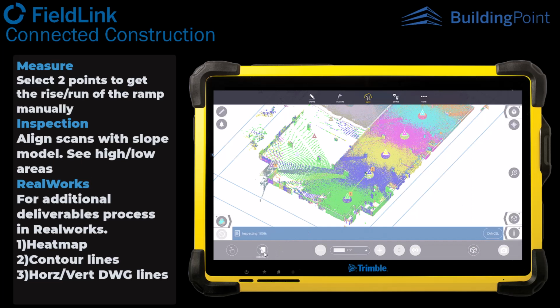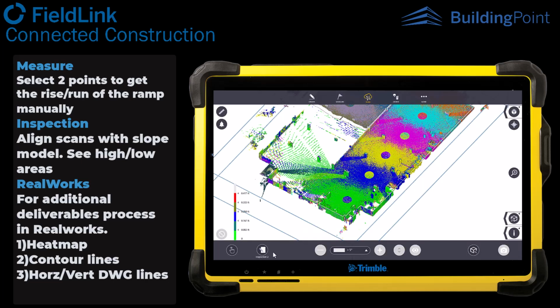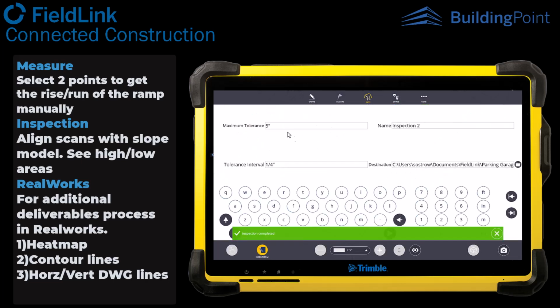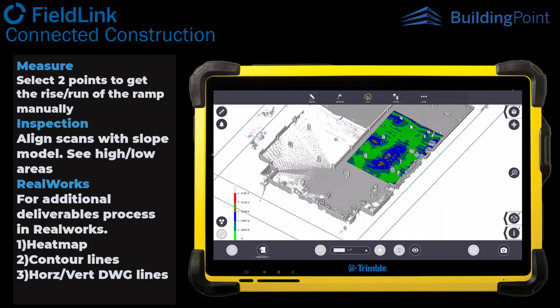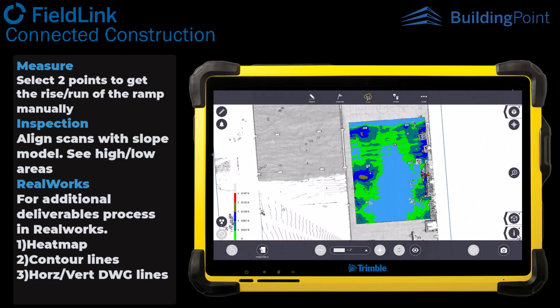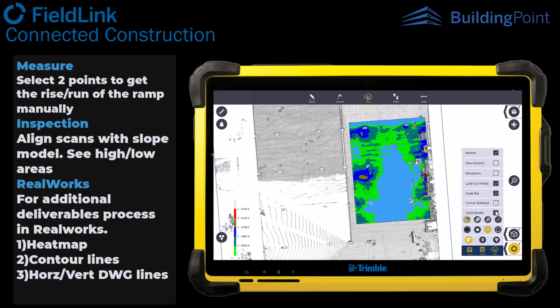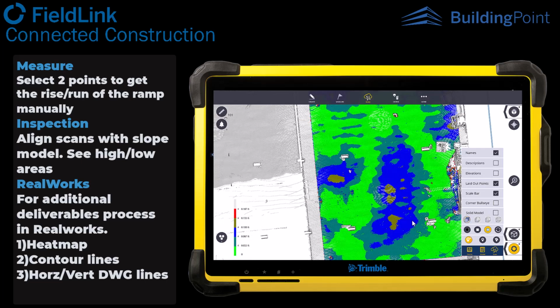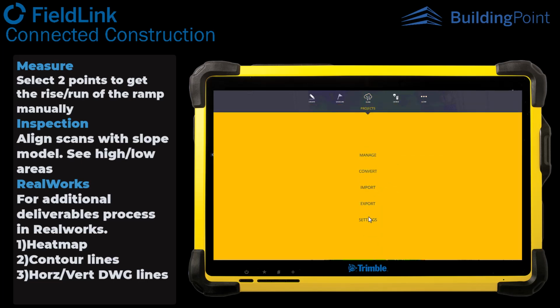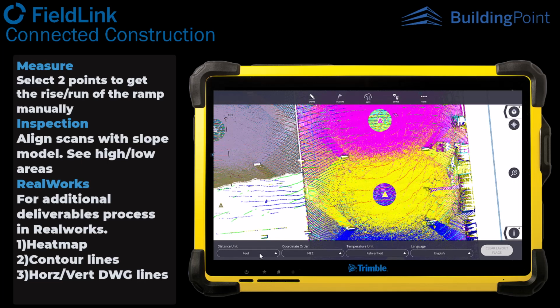When that is done, it's going to just give me the absolute distances and the color of those points away from that model, which, if I align it well, should be usually pretty good for an indication of high and low spots. Depending on how I line it up, usually what I like to do is also turn off the solid model. So here you can actually see some dipping there, whereas the rest of it is very accurate.